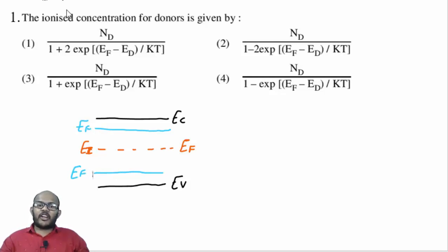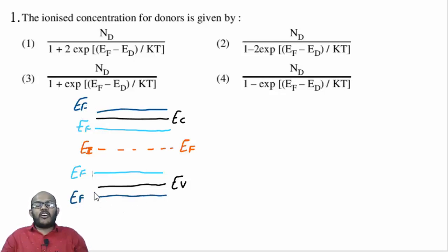In the case of a tunnel diode, you are going to dope degenerately, nothing but you are going to dope extensively, that is, you are going to dope more. So at that time your Fermi level will be crossing the conduction band, or the valence band also. So this is the variation of Fermi level.